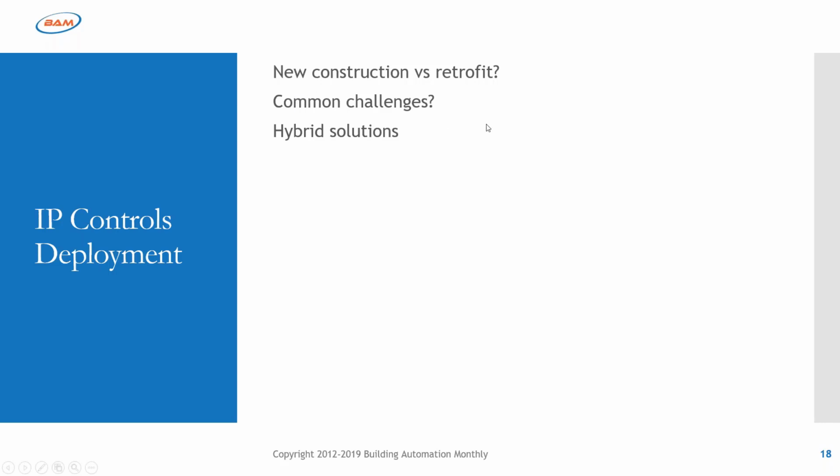So what you typically do is you put the industrial switches in the IDF or MDF, and you'd have enough slack in your Ethernet cable. So this is where you have to direct your electricians. You'd have enough slack in your Ethernet cable that at a later point, once the switches are established, you can disconnect the IE2K. You can run the Ethernet in the cable tray and run it to the switch. That's kind of how I would approach this. The biggest challenge here is just getting through commissioning and functional test and not being someone who's causing the certificate of occupancy to be delayed because of your IP controls.